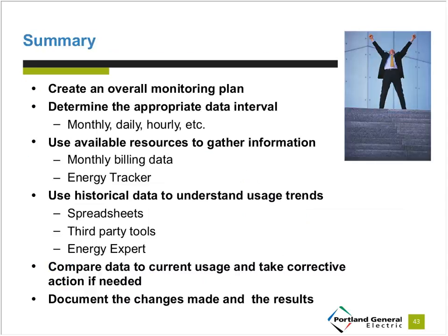So in summary, when you're creating an overall monitoring plan, you have to ask yourself, what do I really want to look at? Do I want to look at monthly data, hourly data, daily data? So what information will be important for you to look at so you can make decisions about how you're using energy? And then once you make that decision, you have to decide, where am I going to get that data? Am I going to get it from Energy Tracker? Do I want to get it from my monthly bills?